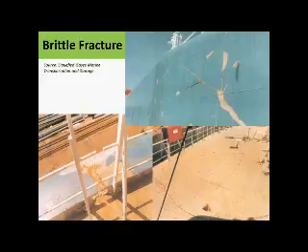Luckily we do not have many major incidents. But you can see this was the brittle crack, which appeared later. Can you see these are brittle cracks on the deck? Is it clear over there? What has happened? The liquid was drained from here while evaporating on the side, and it has very brutally embrittled the steel over there. Although this is a better quality steel on the top, this can happen.